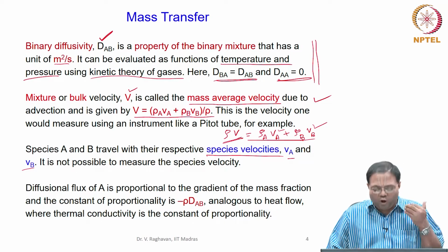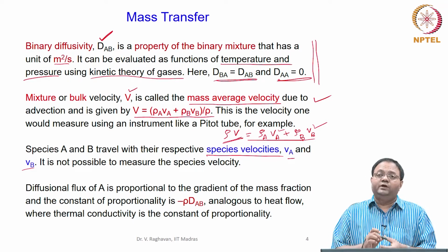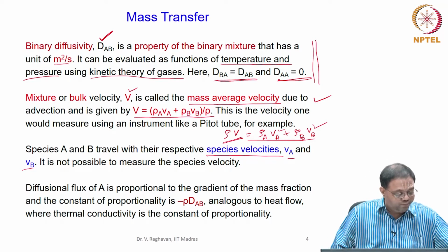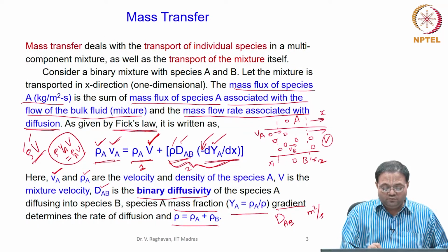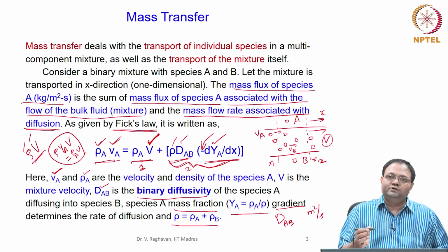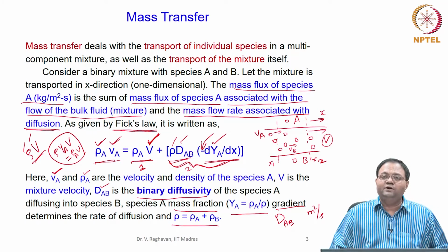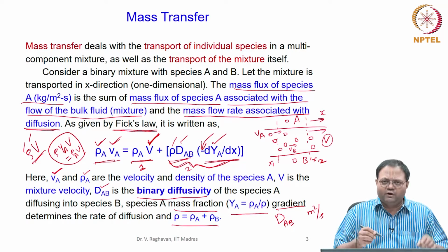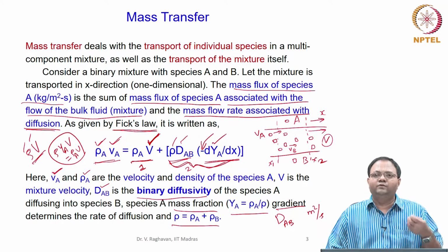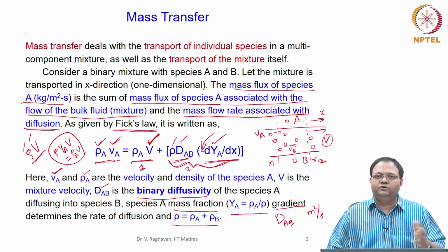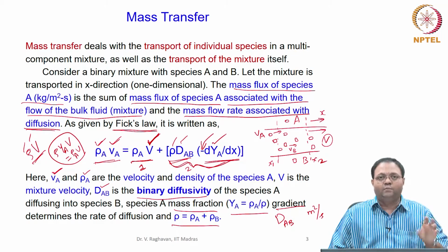Okay. So, then how will you resolve this equation? That is what we are coming to do. See, what you have to do is we can measure the first term. So, density can be measured or it can be calculated. Similarly, mass fractions, if you know, then we can calculate them. We can actually take out the species at a particular point and see what is the concentration of each species in the mixture at that point. Similarly, velocity at the point can be measured.